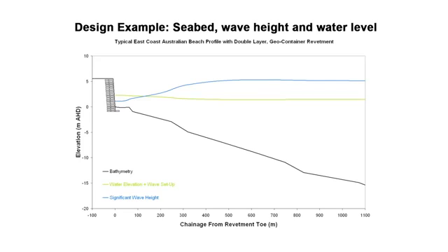The other thing that does happen though, this is our water level, and we might start with about 1.4 metres offshore, but this is where the wave setup process comes in. So as the wave loses height, it gives a bit of its energy into the water level, so the water actually rises near shore, and that's certainly one of the biggest processes in tropical, if you're ever doing any applications on tropical atolls, coral atoll type situations where the wave setup, even though you've got a small tide range, the wave setup brings the water level up over the top of the reef, and then the waves come straight over the top of the reef.